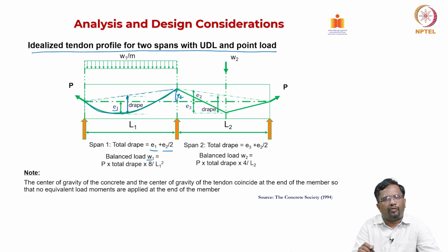So, we have also found the expression for that. We can find the total slope change between the 2 points of this cable profile. Then we can divide by the length and the amount of pre-stress to get your W1 also. So, that is how we found that the vertical component of the pre-stress is proportional to the slope change that is happening per unit length.